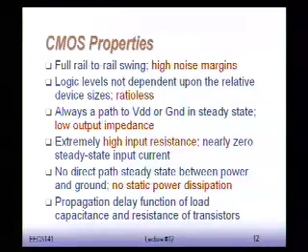In CMOS, what's nice is that you can choose the logic levels independently from the speed, because you know that no matter how you size the devices, your logic levels are always going to be the same, unless you do something really strange. And therefore, the sizing can be done purely for speed. So you have an additional degree of freedom, basically, as opposed to a ratio device. Okay?